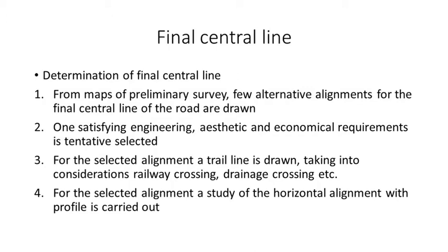Next, high flood level. Next, what are the soil characteristics? What are the geological features? Next, what are the sources of construction material, stone quarries, water source? So all this data should be collected in the reconnaissance survey, and we have to prepare a report on that reconnaissance survey. Okay. Next, after the reconnaissance survey, we go for the preliminary survey.